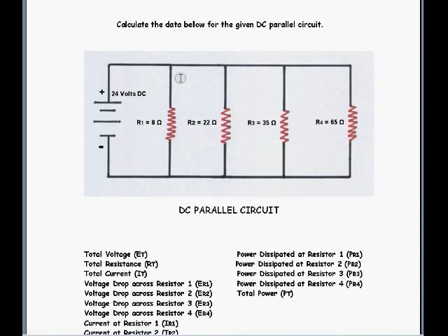But since we have more than two, or say 3 or more, you can use the summation rule, which is 1 over R1 plus 1 over R2 plus 1 over R3 plus 1 over R4, and then you can calculate the total resistance in regards to resistors in parallel, which you cannot add together like you can with a series DC circuit.